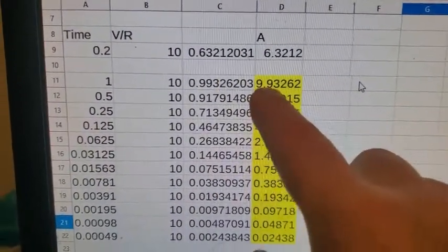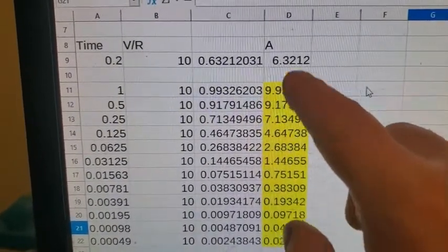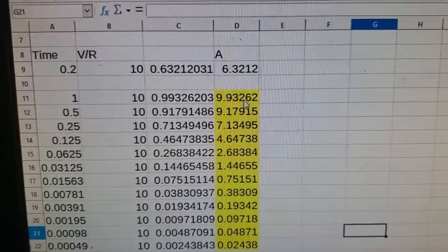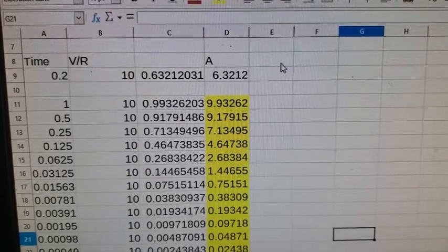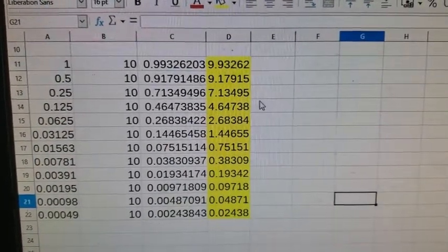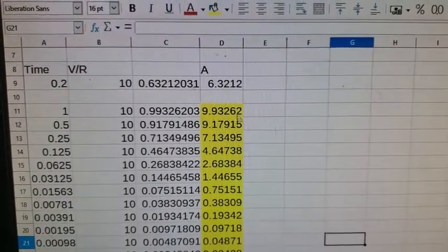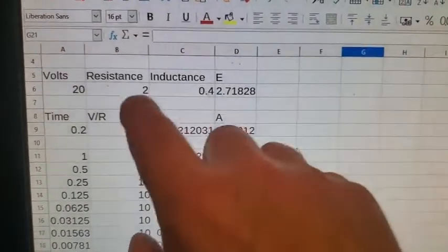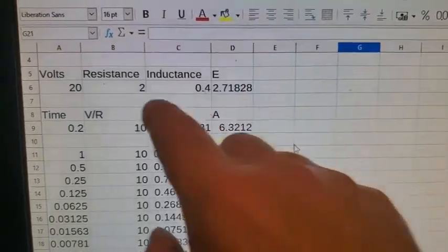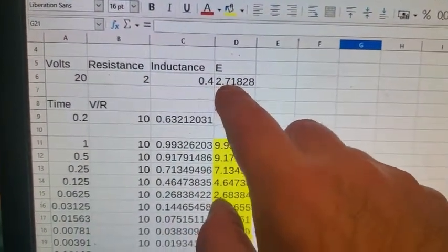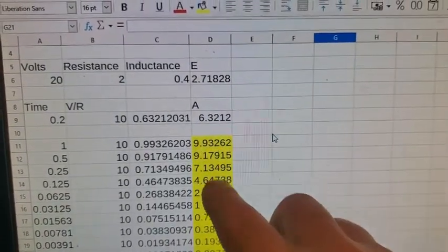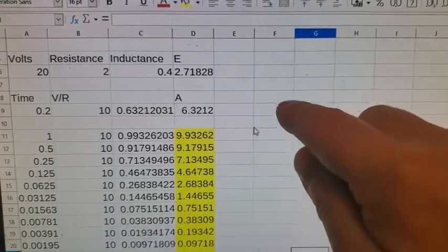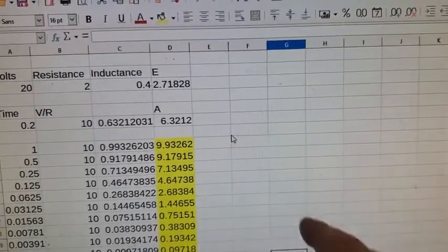So now, this then is the strength of the magnetic field that's established, because the coil is going to be the same with all of these, so the magnetic field strength will be determined by the amps that are flowing through. I don't know if this coil has 10 turns or 10,000 turns, but the amps will determine the amp turns. And of course, if it has more turns, it might behave differently. But we don't know how many turns a coil wound to these specifications would have. Whatever it is, this is what's going to determine the magnetic field strength. And then the magnetic field strength will determine how much magnetic flux you can get, and however quickly it occurs.